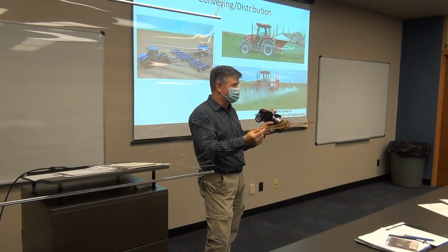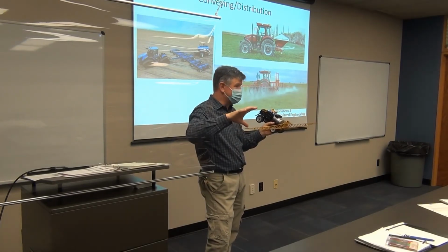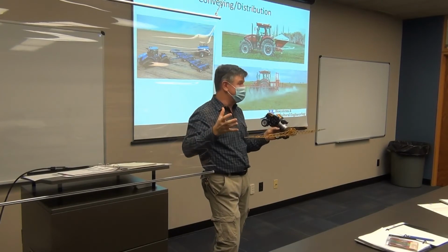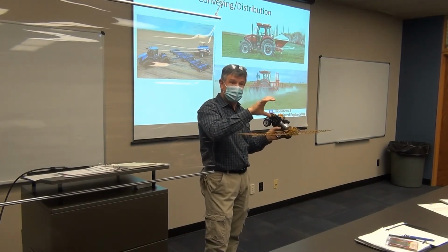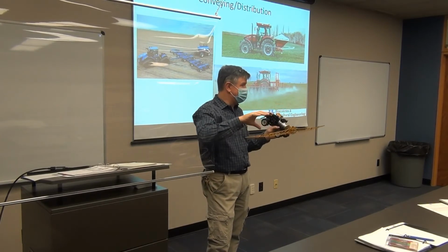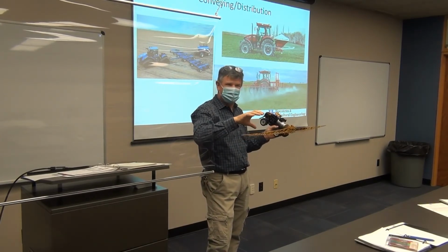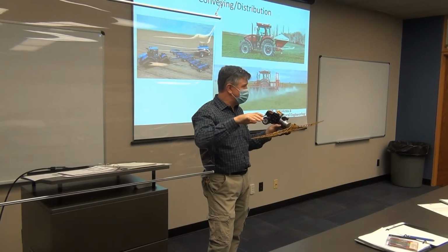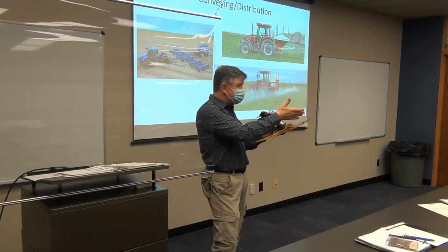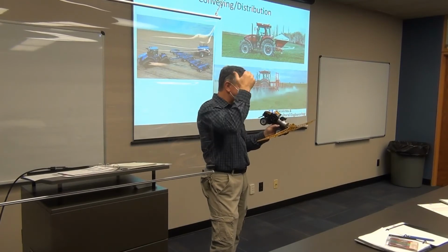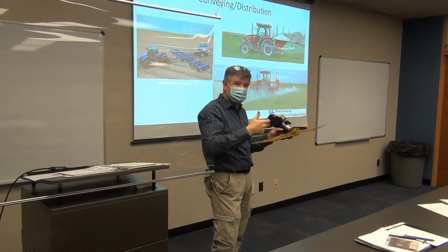So we do some stuff like that. So we use bigger hoses and stuff like that. And generally what the manufacturers do is use fairly large diameter plumbing just so that I don't have those friction losses. So they have a lot more volume than what flow rate I really have to have going through there. So that's kind of how they manage it. So yeah, you're right. Okay, you got the idea. That's the kind of thought process that makes you good engineers.